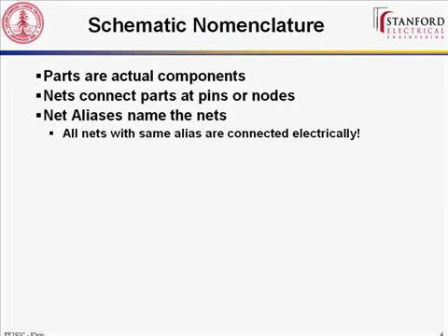That's very important to remember, because you may look at some schematics and the schematic will have parts all over the place and no wires actually connecting things together. All it will do is have net aliases right next to all the pins. Those are kind of hard to read because you have to figure out where these net aliases go, but it still is technically correct. So remember that if you name 2 different things, for example, button 1, they're going to get connected together. So you can inadvertently short nets together by doing this. So be careful.